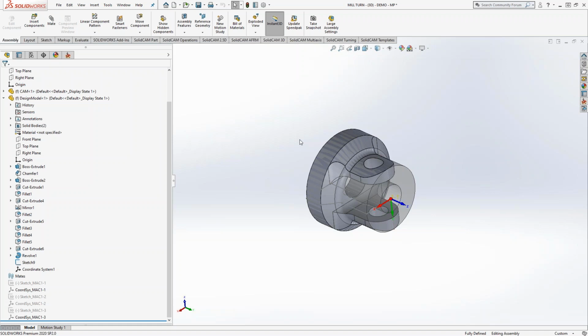And that also holds for assemblies as well. It gets a little more complex on the assembly side, but you have the ability to do configurations of any type of SolidWorks file. So if you had a setup where, like I said, maybe that example of the part you faced it and turned it, faced it and centered it, that could be one setup. How it sits in your custom-made jaws, custom chuck, and then you do a configuration where you suppress those jaws, and now you have another set of jaws between centers.